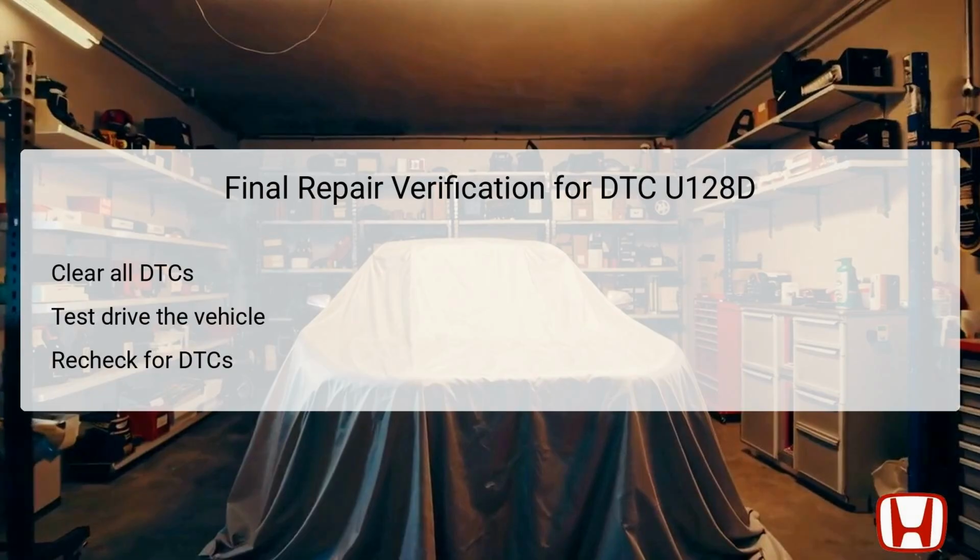After the test drive, it's important to recheck for any stored DTCs. If DTC U128D or any other codes do not reappear, it confirms that the vehicle systems are communicating effectively and that the issues have been resolved.